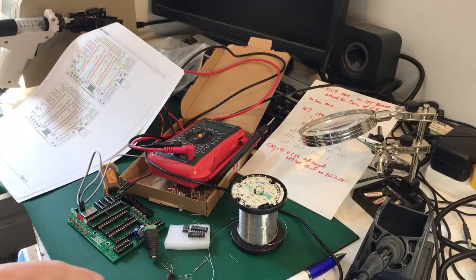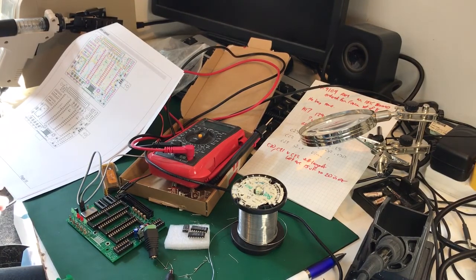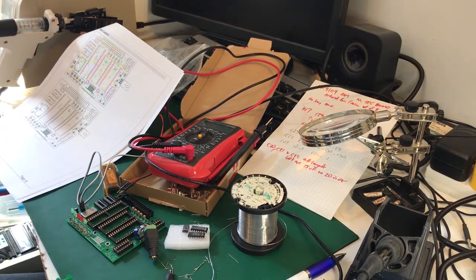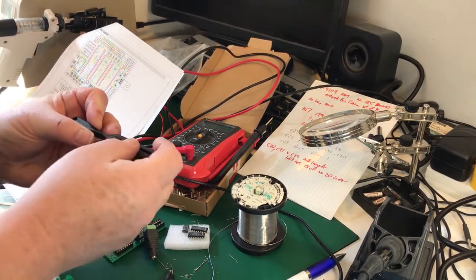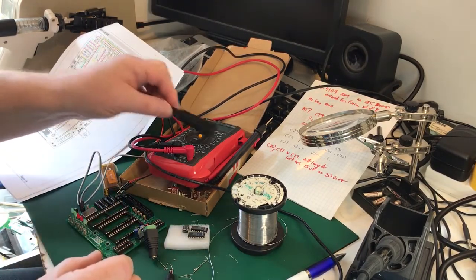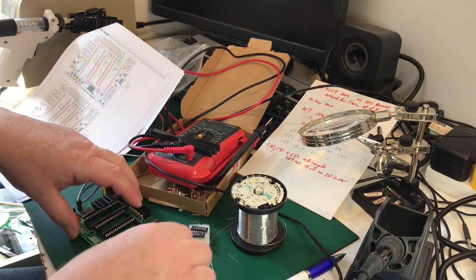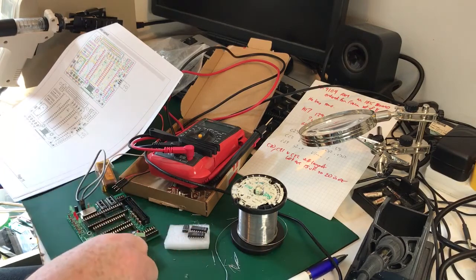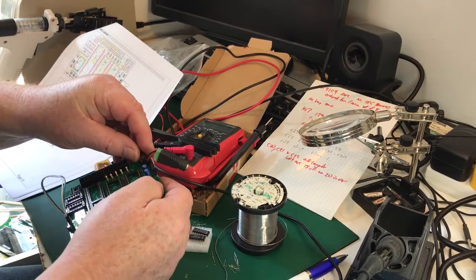Now, everywhere I checked, it isn't actually an LS393. It is supposed to be just a plain 393, which I haven't got in stock, so I'd have to order. But I'm going to power it up with an LS393, at least to test it. It might not be able to drive the circuit, but looking at the circuit I can't see why an LS isn't usable, but maybe I've missed something. So it's disconnected from the power, so the LS goes in that way up, with the pin with notch downwards,